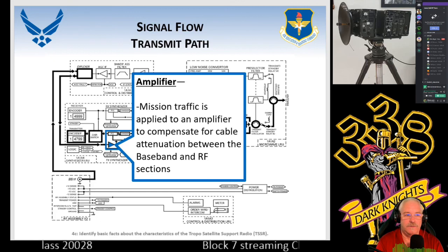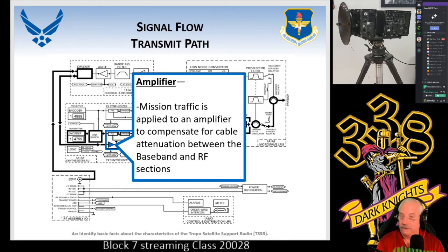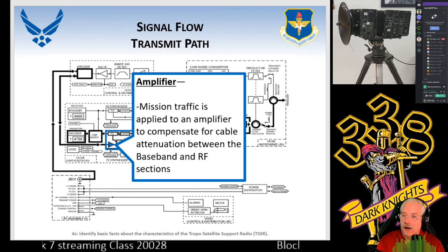This particular device, because either you have a 2-foot or a 150-foot, it is actually called a compression amplifier. This compression amplifier does two things. First of all, it amplifies all the time. However, if you have the 2-foot cable, more than likely you're going to have some compression with it, because there's a threshold of amplification that it's going to do to compensate for just the 2-foot cable, but it's really going to amplify if you got the 150-foot cable.